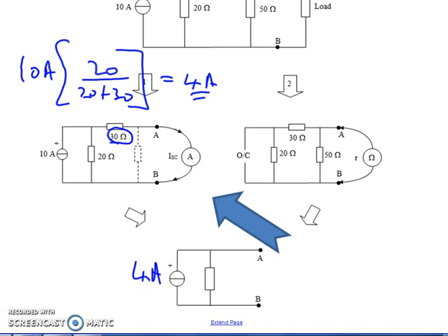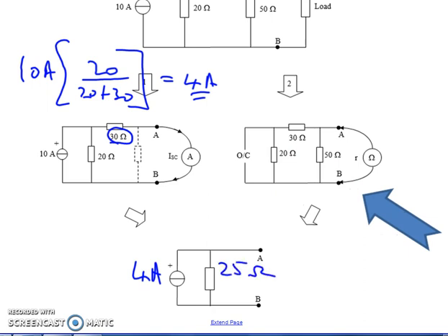It's going to be 4 amps. Looking at the internal resistance then, again, with the generator replaced with its internal resistance, which is infinite, an open circuit, and we measure with an ohm meter at the load terminals, we will see a 50 ohm resistor there, in parallel with which are 2 series resistors of 50 ohms. 50 and 50 in parallel make 25 ohms. So my new resistor down here must be a 25 ohm resistor.